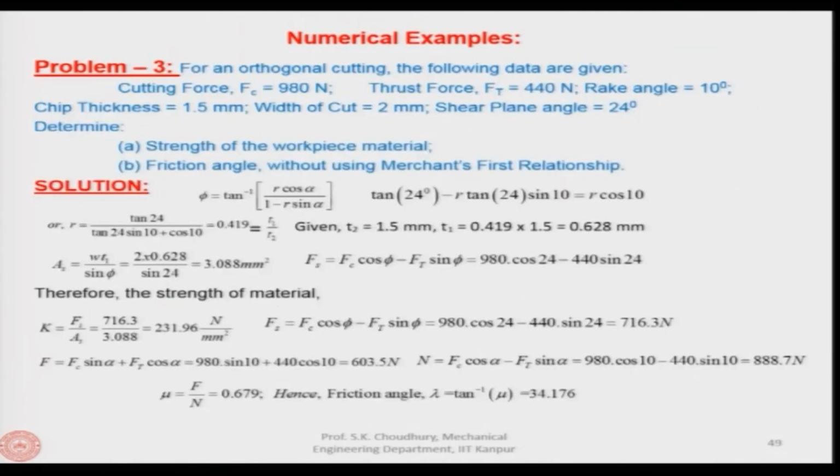Third problem is, for an orthogonal cutting, the following data are given: cutting force is given, thrust force is given, rake angle is given, chip thickness and width of cut, shear plane angle, these are given. Determine strength of the workpiece material, friction angle without using Merchant's first relationship.